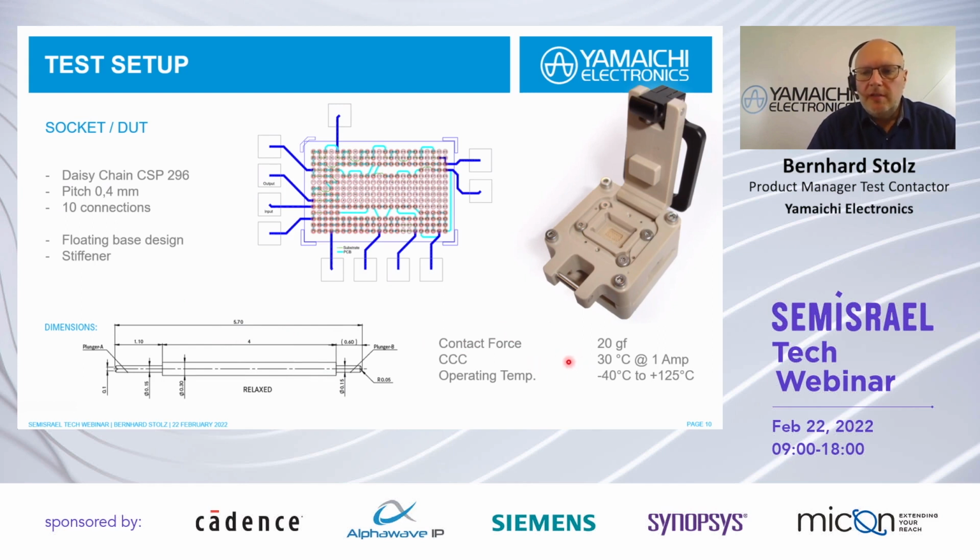The current carrying capacity is 1 amp with a self-heating of 30 degrees, but in this case, for the test itself, it is not so important. What's important is actually the operating temperature. It's specified from minus 40 degrees up to 125 degrees. And as you have seen before, we would like to have a target temperature on the pin of 125 degrees. This means we are actually on the limit of the pin, and so this is, of course, a very important factor. So what happens actually on its limit?